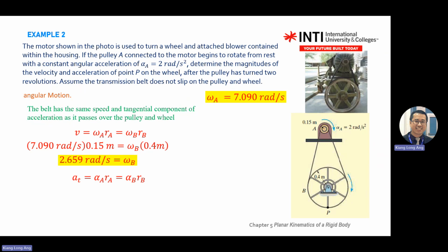So once you know how this wheel turns with omega, you know the V, you know the omega, but one thing you don't know. Again, for a rigid body, you need omega and alpha. For any body, any component or any rigid body, you need two pieces of information, alpha and omega. So if you don't have that, go and find it out. The equation is already written on the whiteboard here. You look at the question, anything that is missing, refer to the equation, then transfer to another one. Just don't confuse omega and alpha. Omega and alpha link to the radius. So as long as the radius changes, omega and alpha will not be the same. But if there is any belt linked to the two bodies, velocity will be the same along the belt. The belt will move at the same velocity.